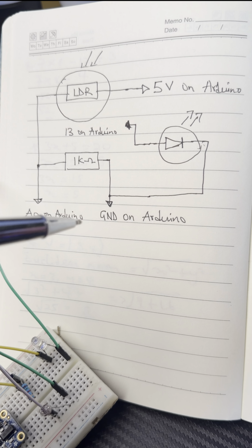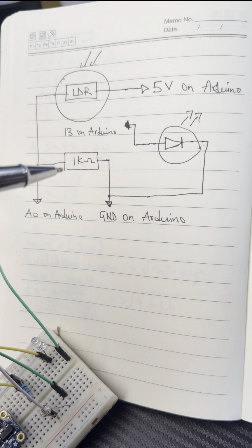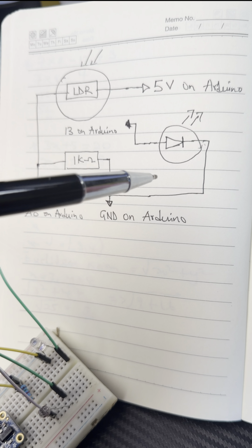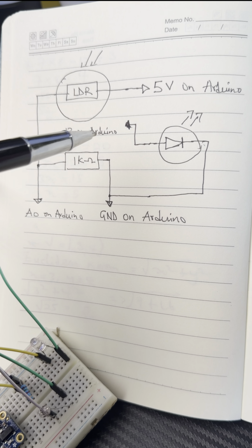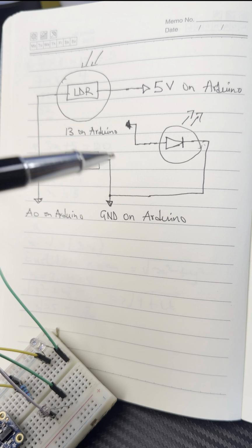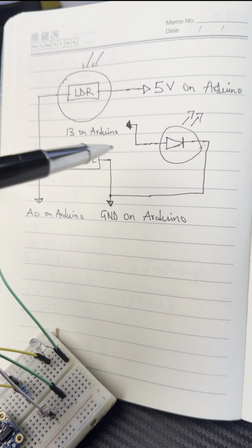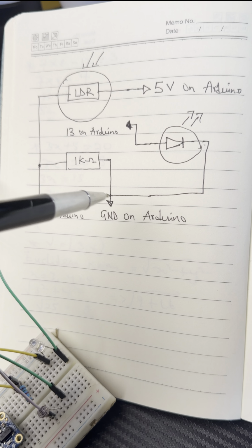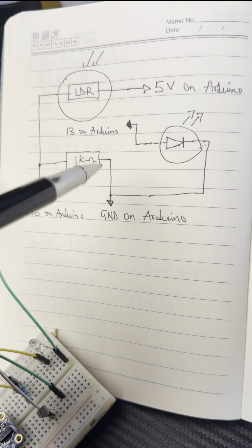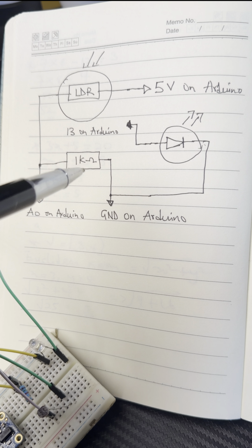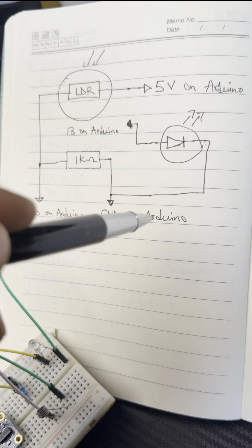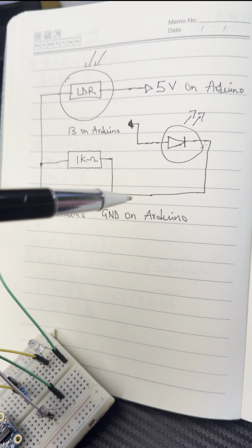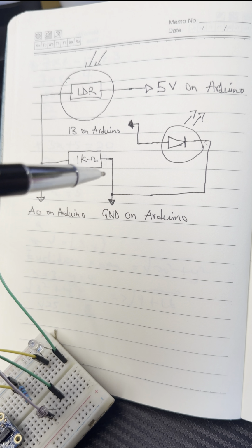After that we are also connecting everything to our LED or light bulb. The positive pin of the LED, which is the anode in this case, is connected to pin 13 on the Arduino board. You can use any digital pin you want, but we are using pin 13. And the negative pin of the LED, we are connecting to ground. You can see it's connected to the same ground as the resistor right here. The Arduino has a lot of ground pins, so you can connect it to a separate ground, but if you are using a breadboard and want to hook it up to the same ground, that works.